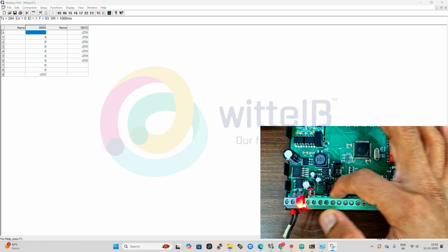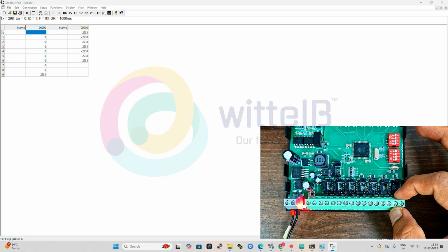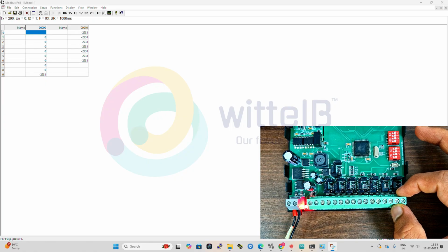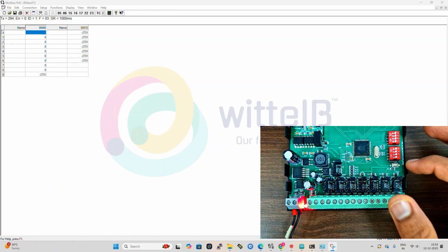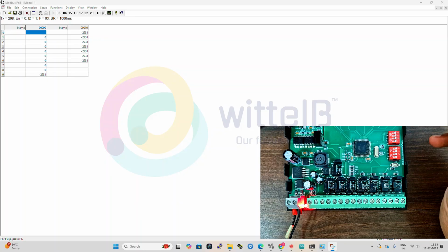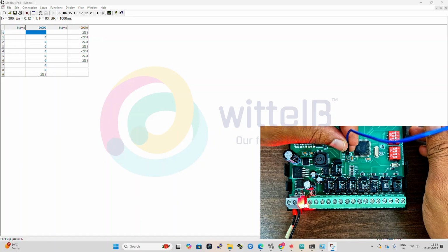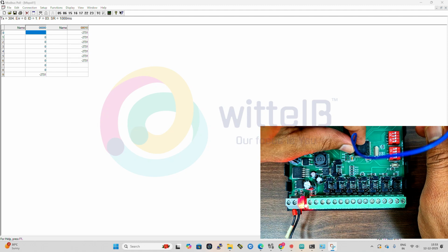And also here we have the reference voltage, that is 5 volt and 10 volt. Just by shifting the jumper, it will be configured with the different voltage. And also for the AI NTC, by default it's AI. So now I need one male-to-male jumper. To check this, we need one reference voltage, that is 5 volt. In this board we have the 5 volt reference marked.